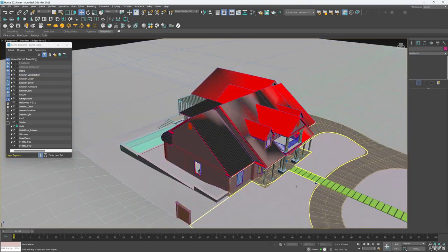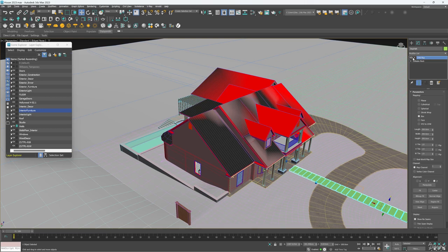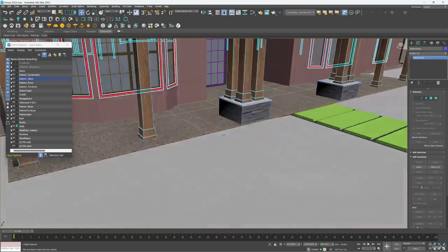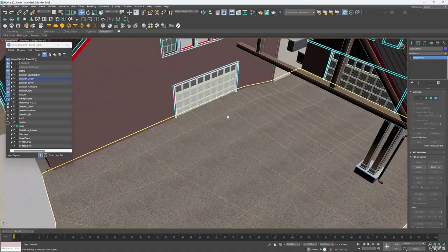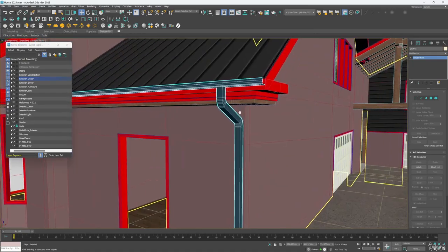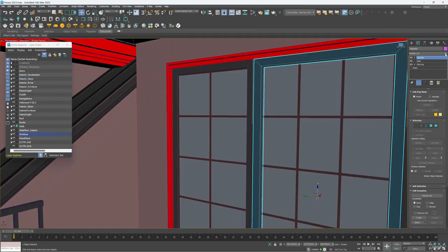Almost all elements of the scene are textured with the UVW Map modifier in box mode. The value of all sides is 100 or 200 centimeters. This is a quick method of texture mapping simple geometry objects, such as roof, windows, walls or columns. The UVW Map modifier is also applied to all painted objects or metal objects.